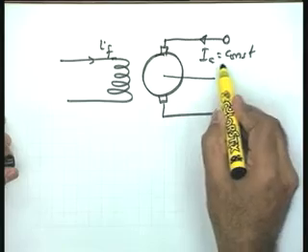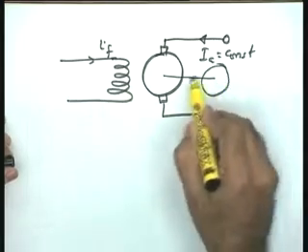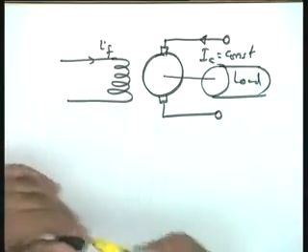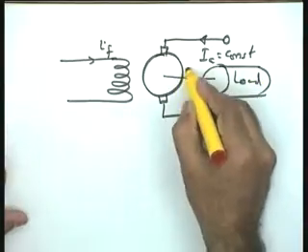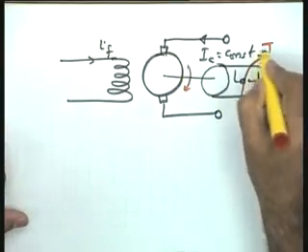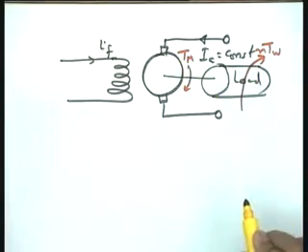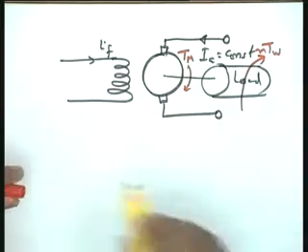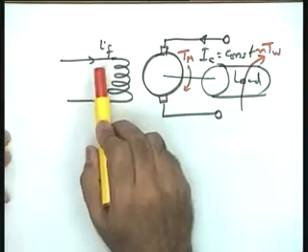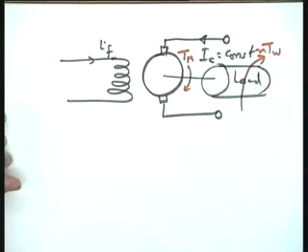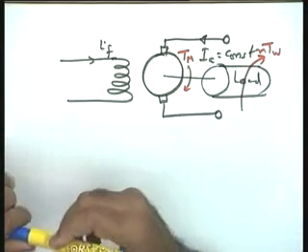You can take the same scheme here, yes, you could take it this way: load, and there may be a disturbance on this particular load, TW or NTW as you may like to take. Tm is the torque developed by the motor. In this particular case this torque is dependent on the field current, since I am keeping the armature current constant. I am giving this particular derivation to highlight what are the applications of field controlled motor vis-a-vis